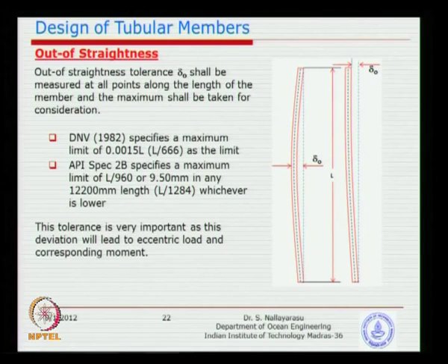You can make that in some classes of structures like aircraft structures, but if you look at their specification, they may not even insist on this, because it is more important to have the shapes and sizes correct. So, in offshore structures we say 9.5. If you come to onshore structures, you may have slightly less stringent limits, depending on the criticality. You fix up this number and then make sure that the contractor follows.